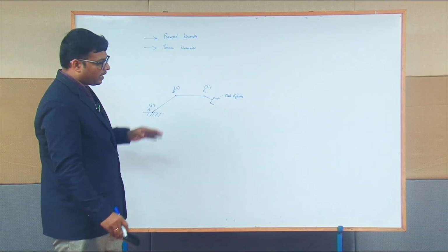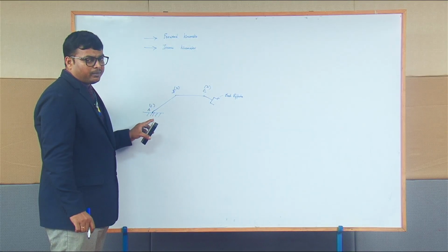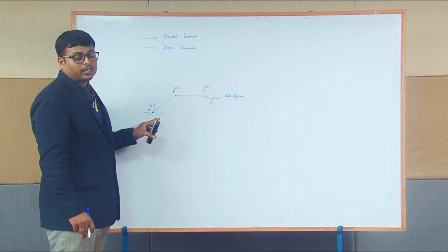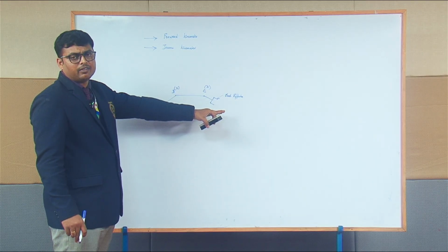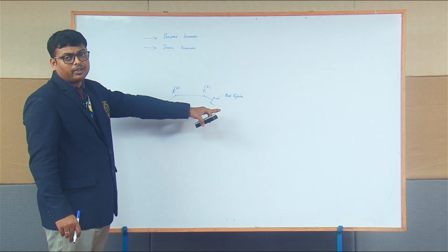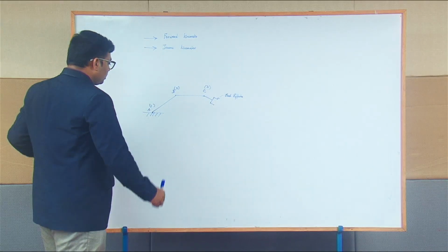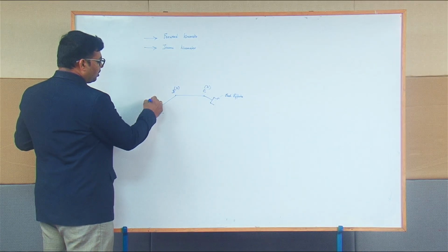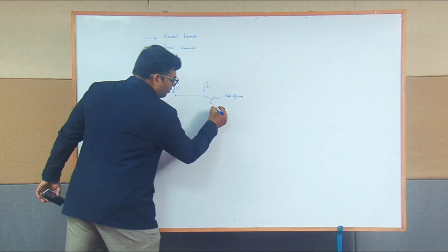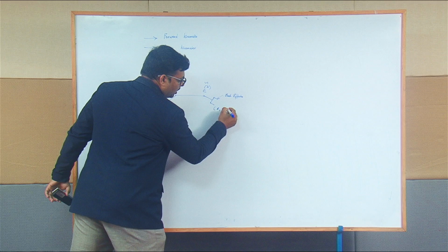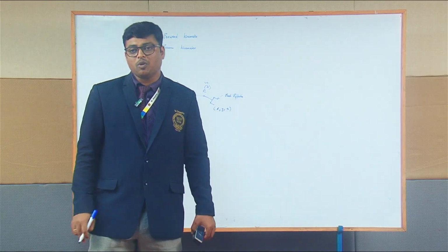So what is forward kinematics? Knowing the displacement variables with respect to the joints, if I am able to compute where the end effector is located, we call it forward kinematics. Again, if the joint variables 1, 2 and 3 are known, I will be able to plot where this end effector is in 3D space, the x, y, z coordinate.